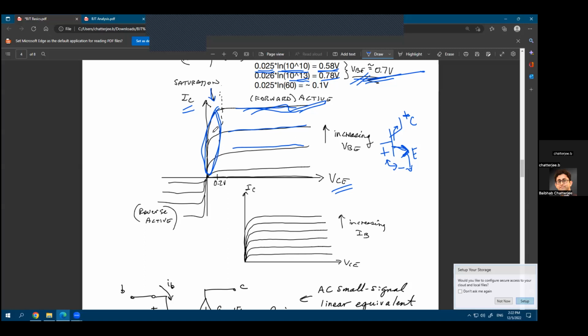And the way the transistors or the BJTs were first described, this is the way it had been described: okay, we have a saturation of carriers in the base region when your VC is low, and that's why you are calling it a saturation region, right? So it's a different kind of saturation. It's not that the current is getting saturated. The current is getting saturated here. So it is very easy to understand in case of MOSFETs. In case of MOSFET, this is called the saturation region or the active region because your current is saturated. In case of BJTs, this is called the saturation region because in this region, you have a saturation of carriers